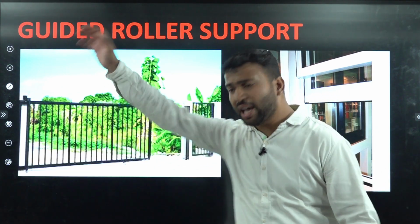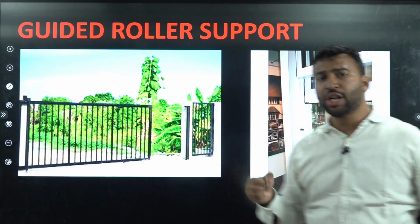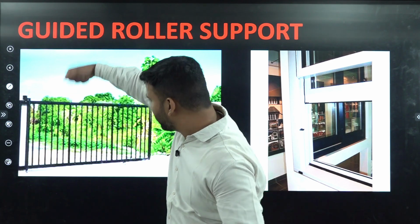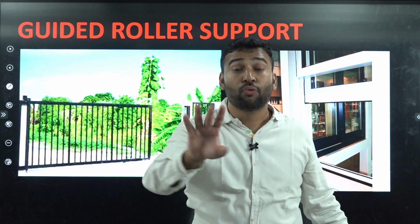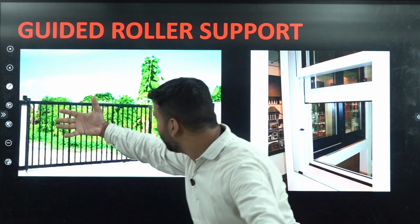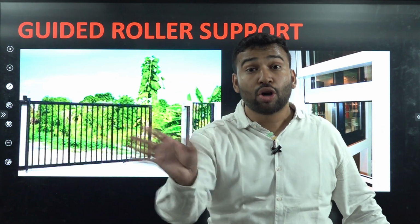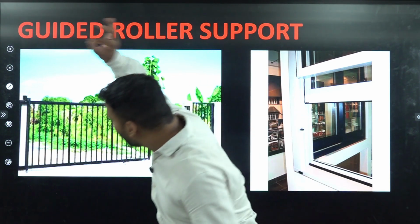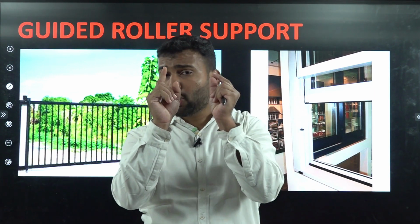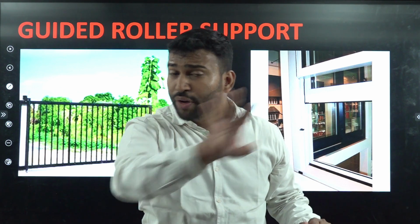Okay, suppose, students, I have a sliding door or a sliding gate here, and if I try to pull that particular sliding gate in the horizontal direction, it will move very easily. But if I try to move that sliding gate in the vertical direction, it will not move because it will give me a vertical reaction in the downward direction. Similarly, if I try to rotate that sliding gate in the circular direction, it will not rotate. Why will it not rotate? Because rotation is not allowed in case of guided roller. So you have received a very good concept here that at each and every guided roller, no rotation is allowed.